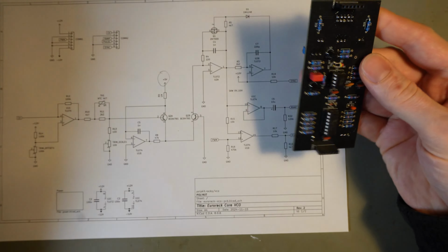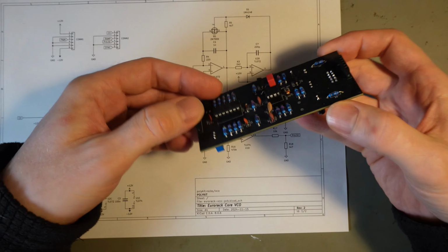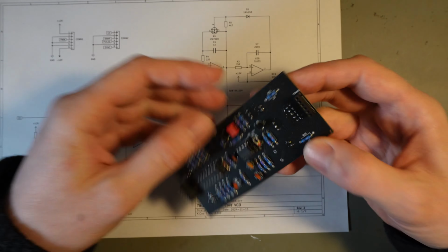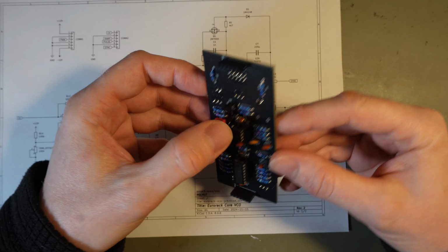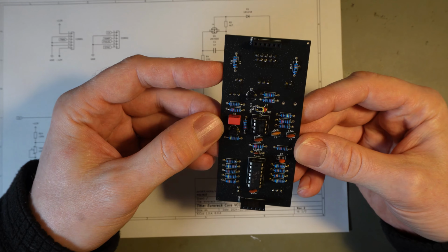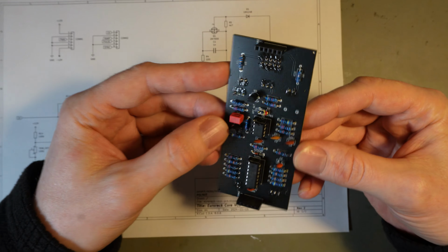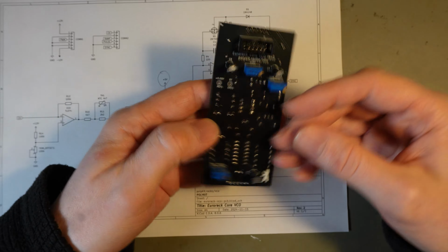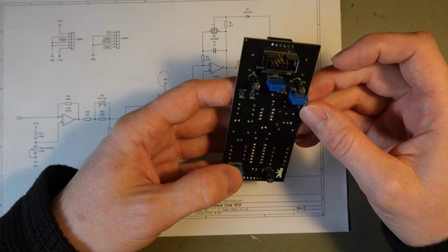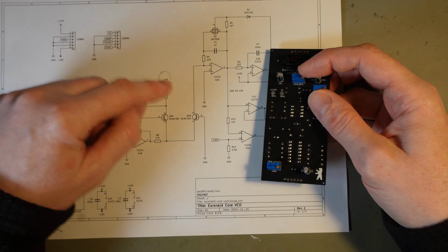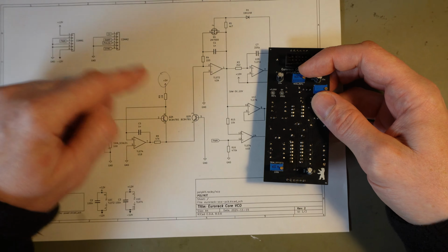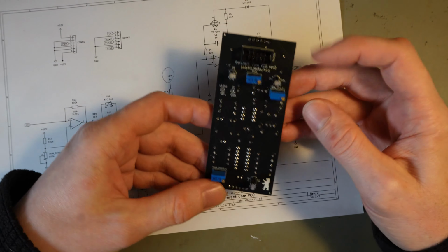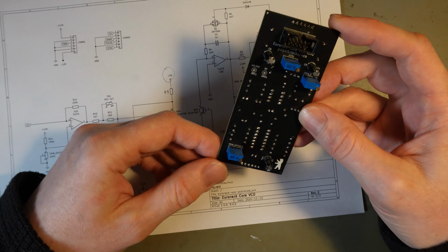Maybe a quick look on the PCB here. What you can see here is the SMD dual transistor, and I put the thermistor very close to it. So temperature changes hopefully will be cancelled out. And here the trim pots. Also you need a precise reference voltage here for the current sink. This is also important, so that can be adjusted here, and trimming for scale and for the offset.